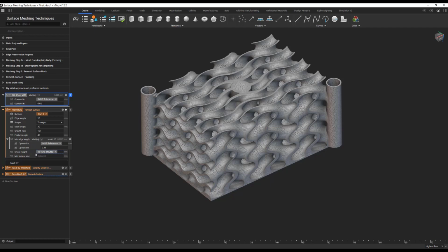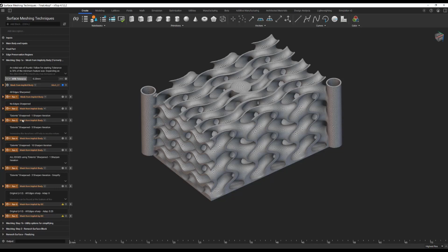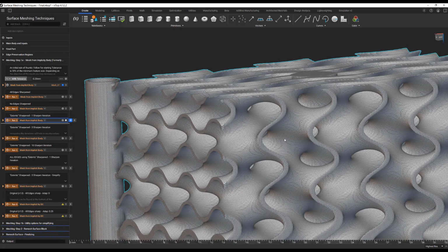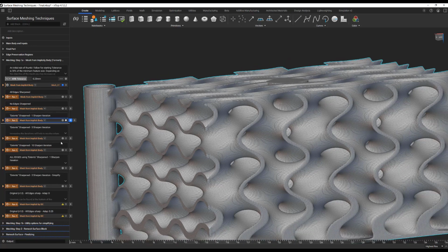So it's going to read in the mesh from run 3, look at each of the elements, find its centroid essentially, and while it goes through and decimates and remeshes, it's going to measure where that centroid changes from its original location and either remesh or keep that element as it was.